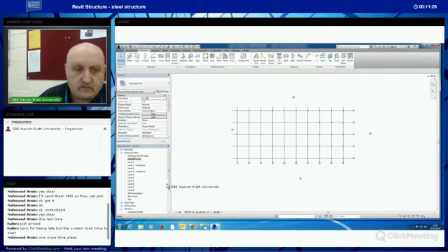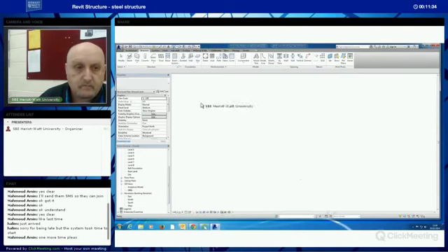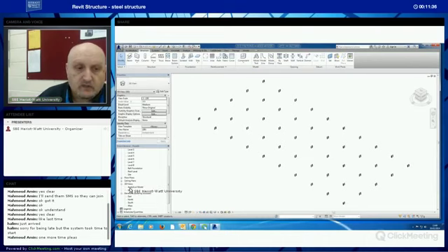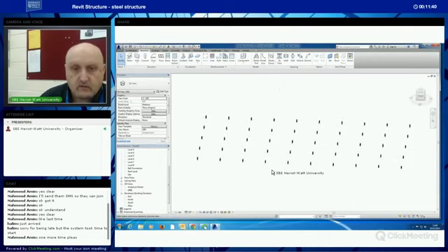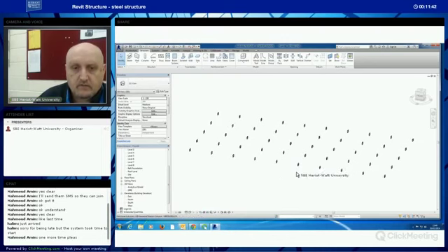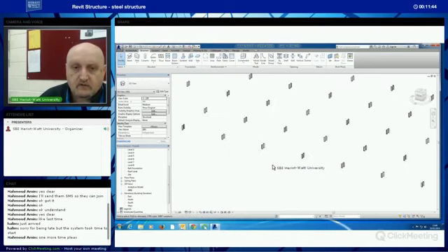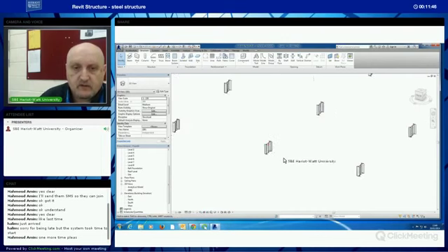Now they're quite hard to see, so I'm going to look at this in 3D for a second. Now using the structural template, there's no default 3D view, so I'm going to put the default 3D view in, and it's populated the project browser, and this is the 3D view. Now these columns, I'll zoom into them, I'll show you 1 or 2 wee problems with them.